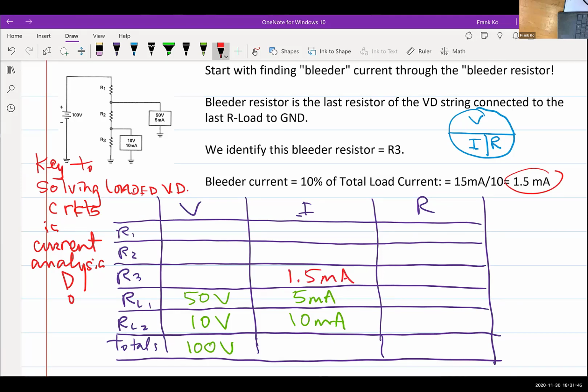And let's go ahead and use the electron current, because the electron current flows from which side of the source? Negative. It flows from the negative side of the source. So electron current's got to flow down, yes? It flows down and it hits the symbol. What's the symbol at the bottom of the source? Ground. So does it die there, or does something interesting happen with current? The current comes over here and flows up this resistor as well as up through this load.